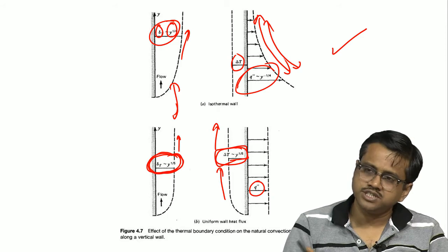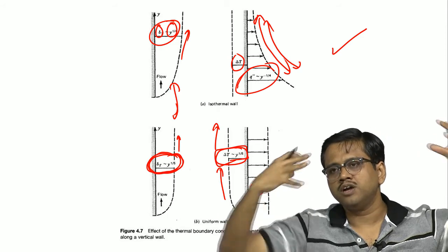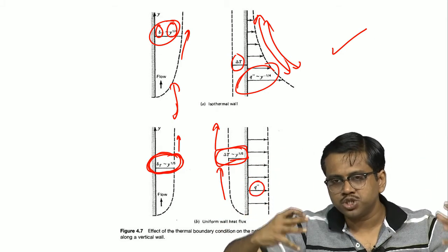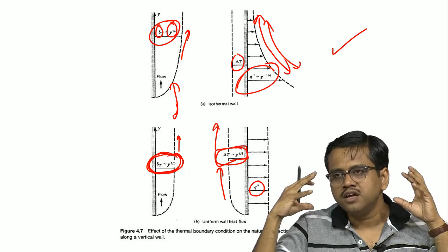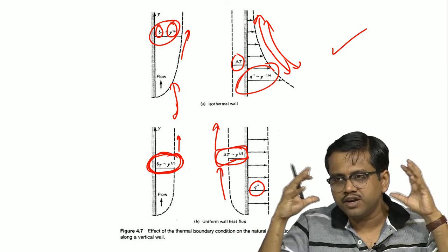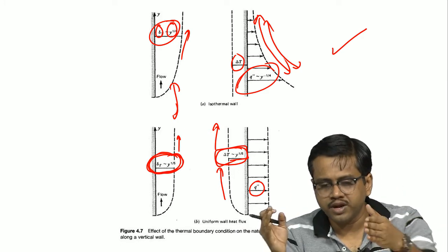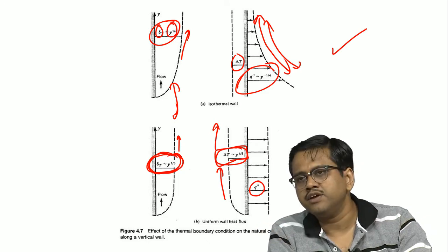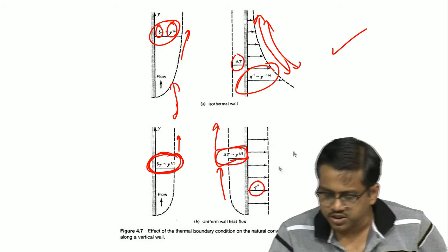So, this gives you a good idea of how the isothermal wall and the uniform heat flux profiles should look, how the temperature should vary, how the heat fluxes should vary. This is an important visual concept, because you have got all these expressions. Now, you need some kind of a visual feeling for how this profile should look. If you do the math, you can easily identify these things yourselves, but even if you do not do the math, these are the kind of profiles that you will get, which all comes from scaling, all comes from the mathematics that we did so far.